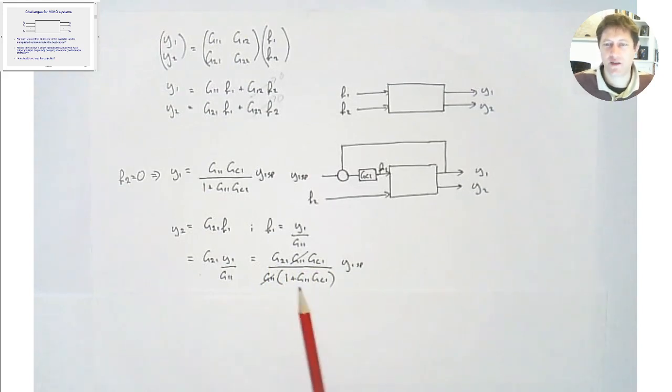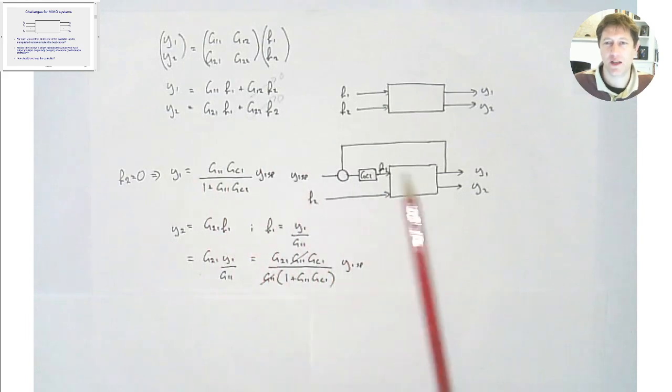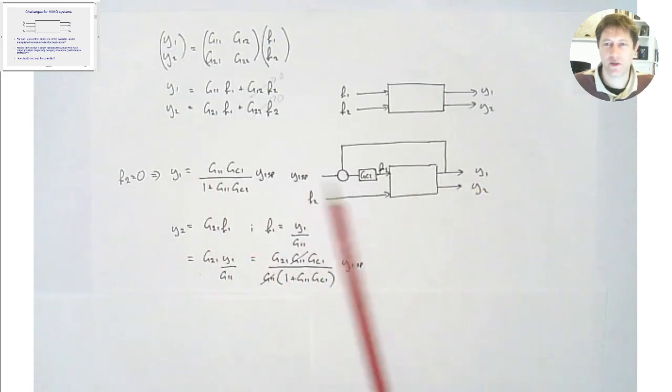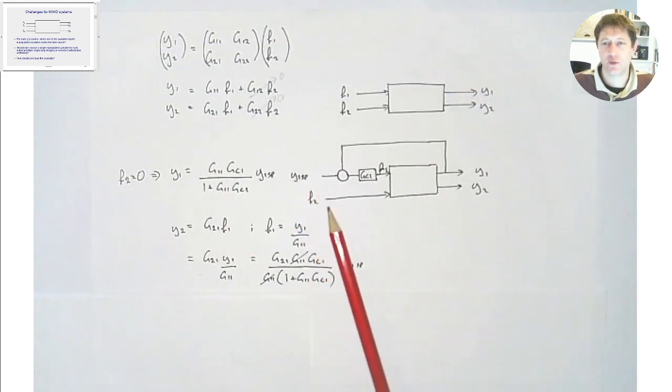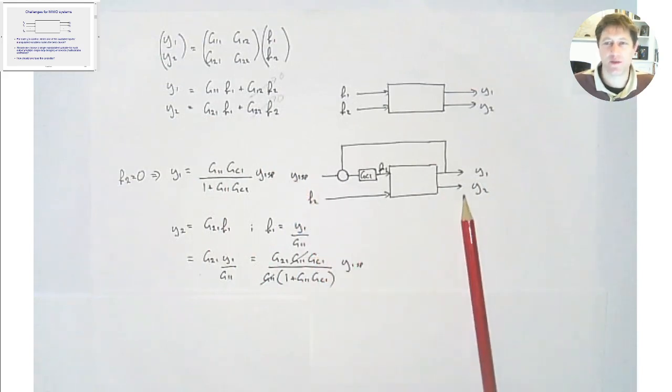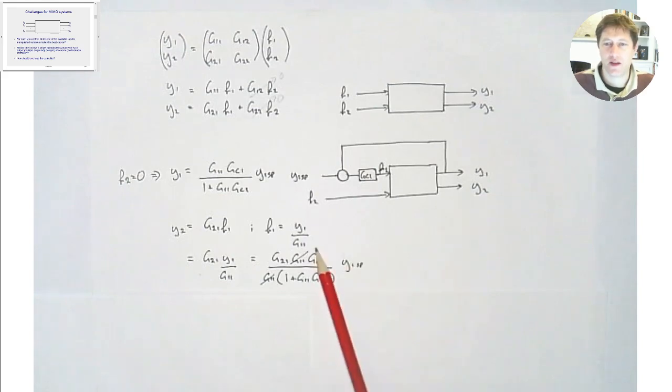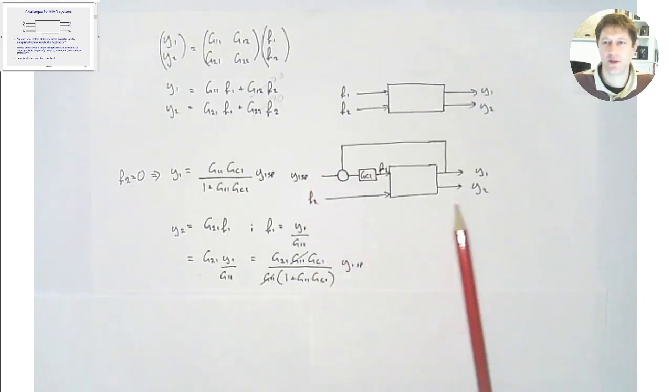And so that's the effect that we don't want to have. This is the effect we do want to have of our controller. Our controller is enabling y1 to be controlled by a set point, but the effect of doing that on the overall process is that y2 is going to be affected too. And it's affected by the controller, GC1 here. So the process of adding a controller means we've now coupled this one to this one.